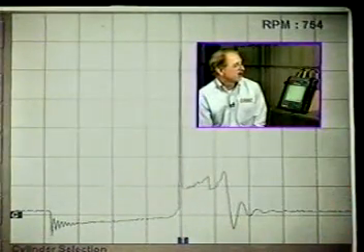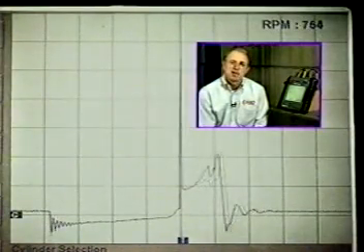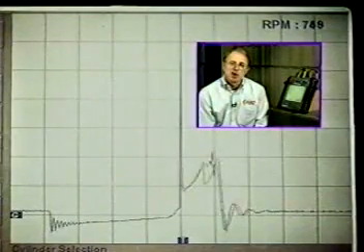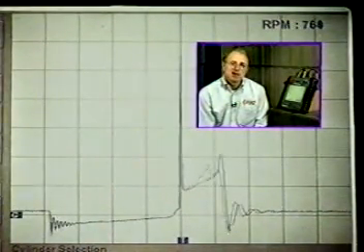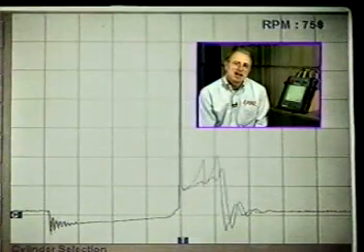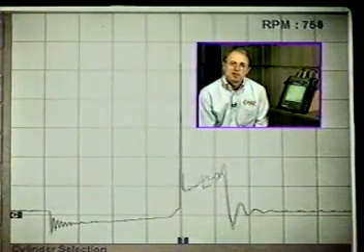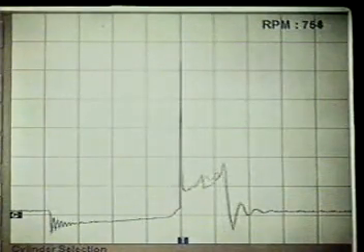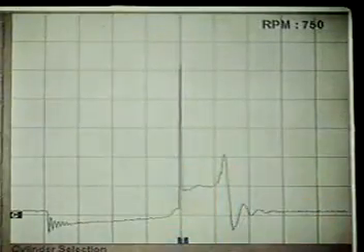We bring up number 2, and you can see it's showing us a problem. Notice that the spark duration period is barely 1 millisecond. Obviously, that's well below the 1.3 minimum that we're requiring. As you can see also, when you look at the spark line, it is in fact bending upward, indicating a lean condition inside that cylinder. Now, this is a case where the car is in park, no load. If we would bring this car out and drive and power brake it, you would see the angle bend abruptly upward more. But let's go ahead and look at all the 6 cylinders here.